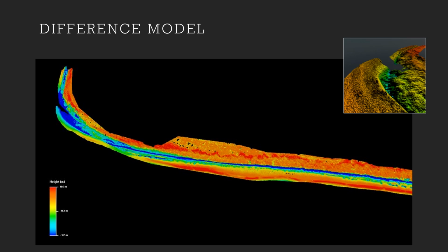So this is the output model, just a segment of the island that I'm showing you from looking at the differences utilizing their combine and compare terrain layer tool. This is representing that elevation change for the western segment of the island. And you can see in the legend there, sorry, it's a little small, but ultimately the negative values are represented by the greens and blues here.